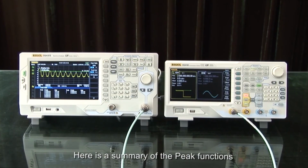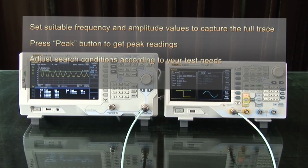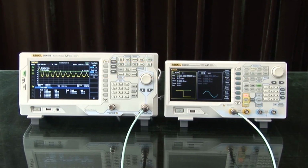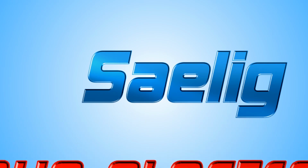Here is a summary of the peak functions. Set the suitable frequency and amplitude values to capture the full trace. Then press the peak button to get the peak readings. You can adjust search conditions according to your test needs, and then observe multi-peak readings at one time.